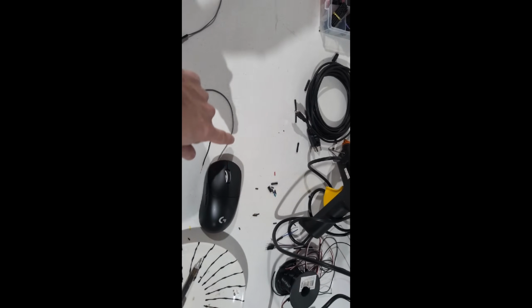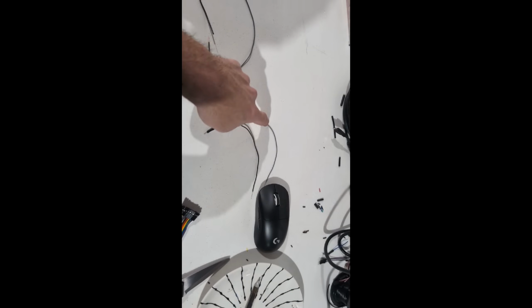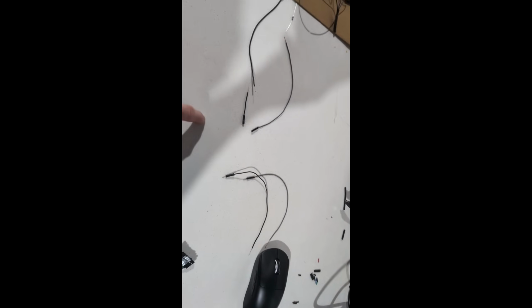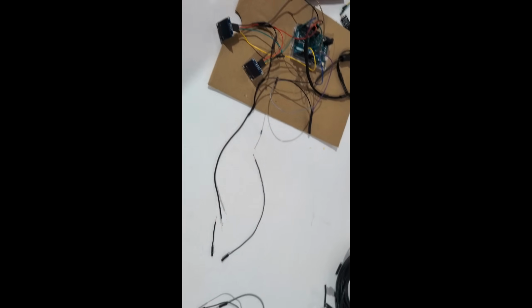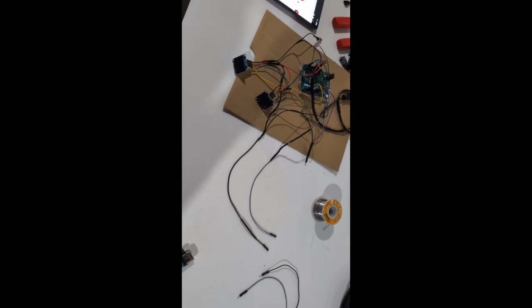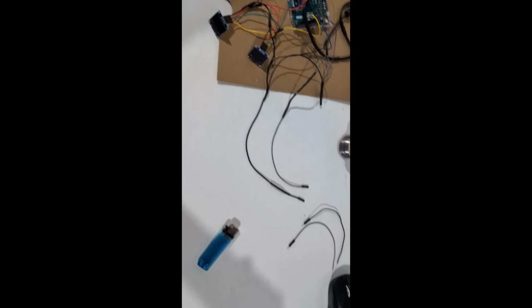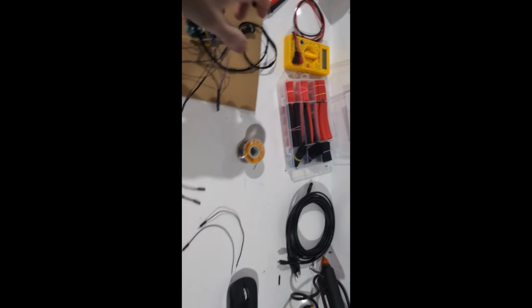And then yeah, we'll have earth for the mouse switch. So we'll have 3.3. The grey is going to be 3.3 volt from the mouse switch. And then the black is going to be earth from the mouse switch. Should go to earth here to the normal earth. That's pretty much it. Right, so that's what that looks like. Now is the hard part. We're going to have to get our multimeter.